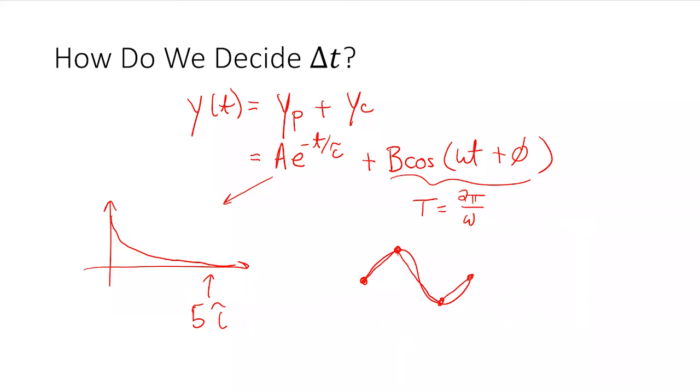So what did I tell you at the very beginning about drawing a sine wave? If I want to draw the sine wave right, how have I always told you to set up your t vector in all of the graphs you've made in the homeworks? Well, yeah, I usually do something like t over 100 or t over 1,000, something like that. All right, that's kind of a delta t, isn't it? That's a time step that I gave you, right? Now, why did I choose that?